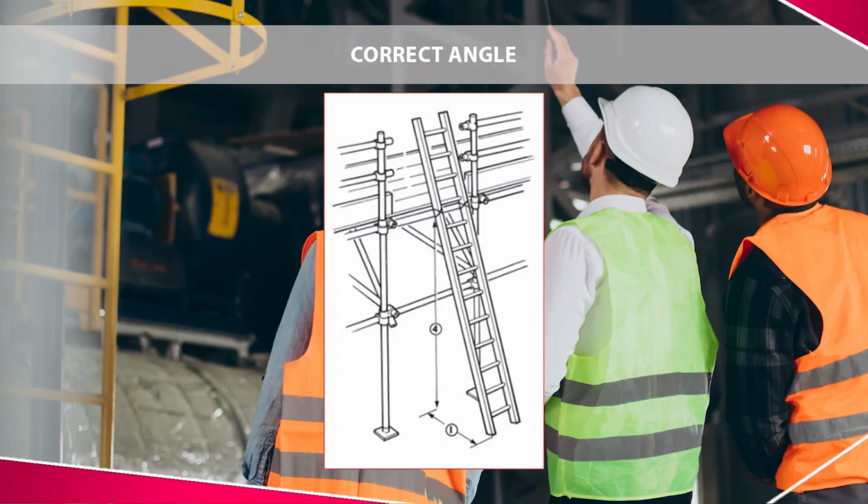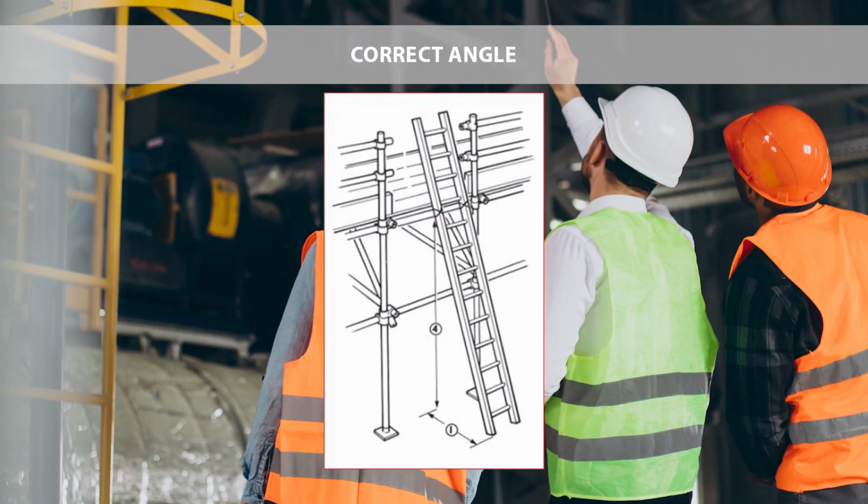To avoid hazards while using ladders, we have to keep ladders free from oil, grease or other slippery hazards. Use ladders only for the purpose for which they are designed. Before placing a ladder, we use the 4-to-1 rule.